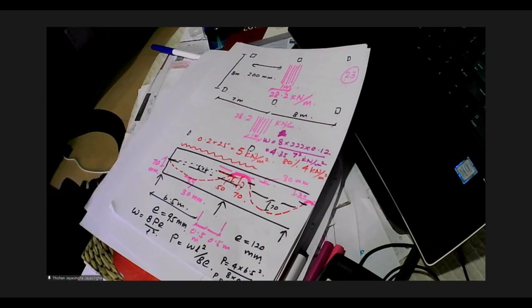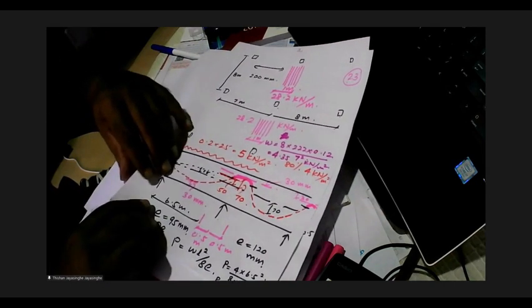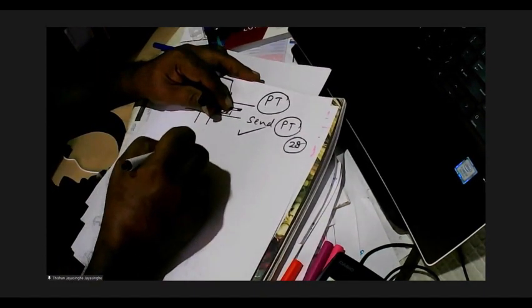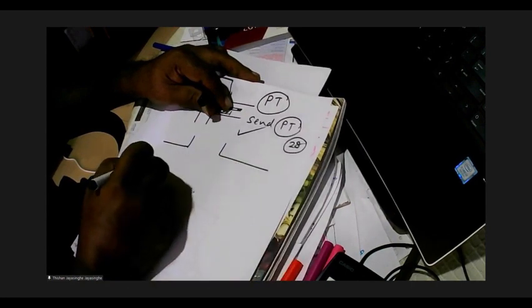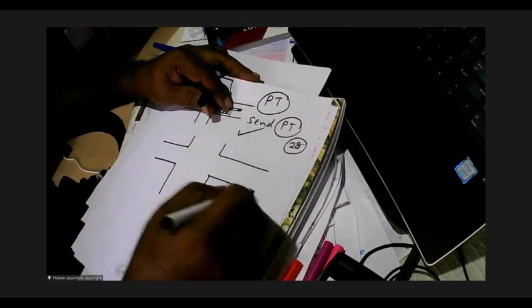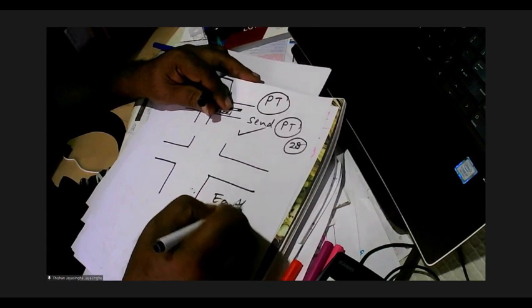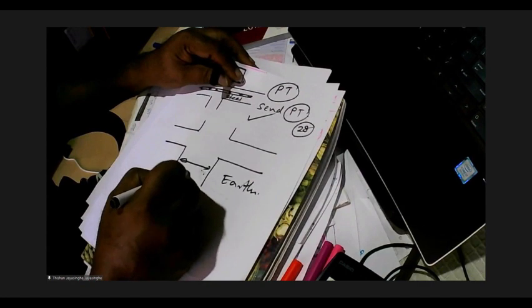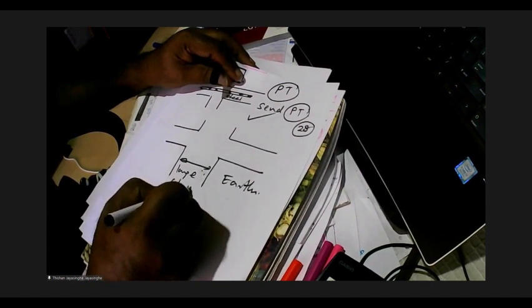And after doing all that, you have to do a shear check and see whether the slab can be subjected to shear failure, because flat slabs can fail in shear, especially under earthquakes. So it's a good practice to make sure the columns are large. So what happens when the columns are large?